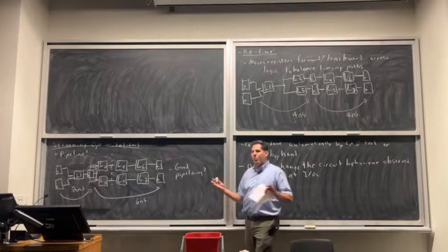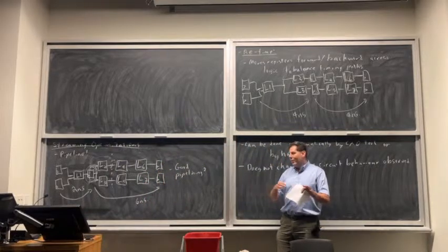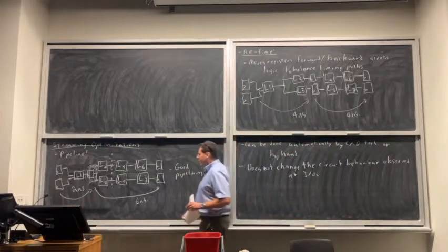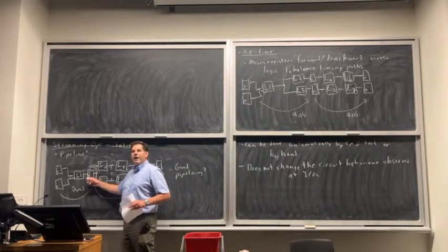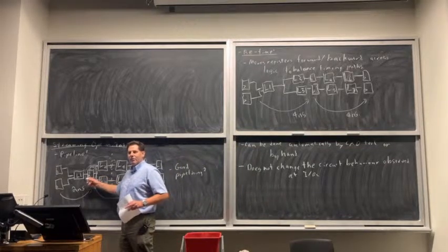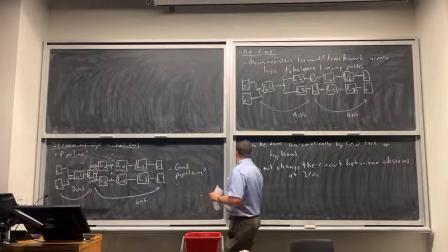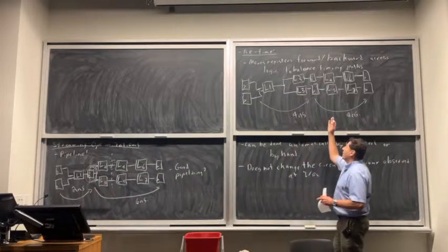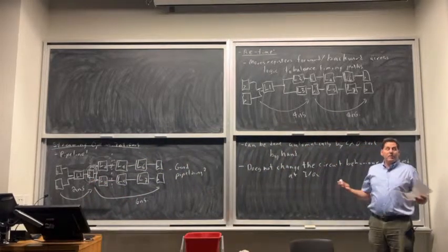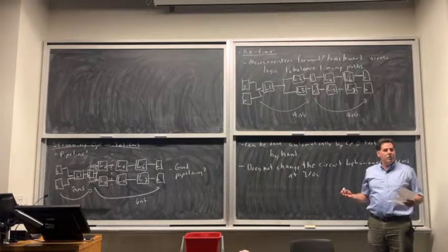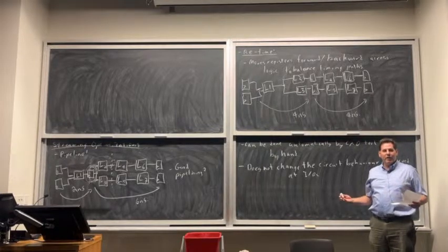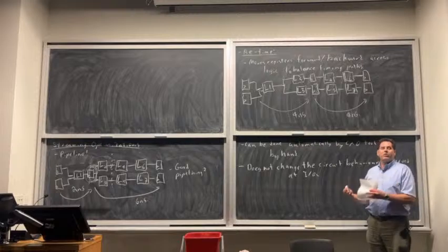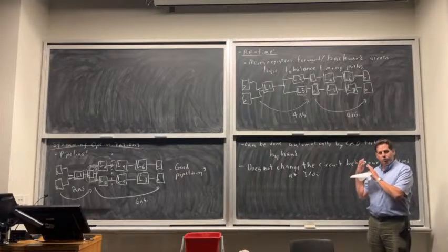If you bring up waveforms, you can say, oh wait a sec, for these inputs this register should have been this value, and it's not that value, so I've got a bug, and I've got to go and look at it. Once you move this register to this new spot, it's much harder for you to reason about it. It's no longer a register that's in your HDL. It's not registering some signal that you wrote and understand.